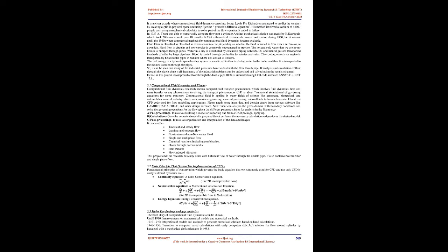Masliyah et al. studied heat transfer characteristics for a laminar forced convection fully developed flow in an internally finned circular tube with axially uniform heat flux using a finite element method. For given fin geometry, the Nusselt number based on inside tube diameter was higher than that for a smooth tube. Also, it was found that for a maximum heat transfer there exists an optimum fin number for a given fin